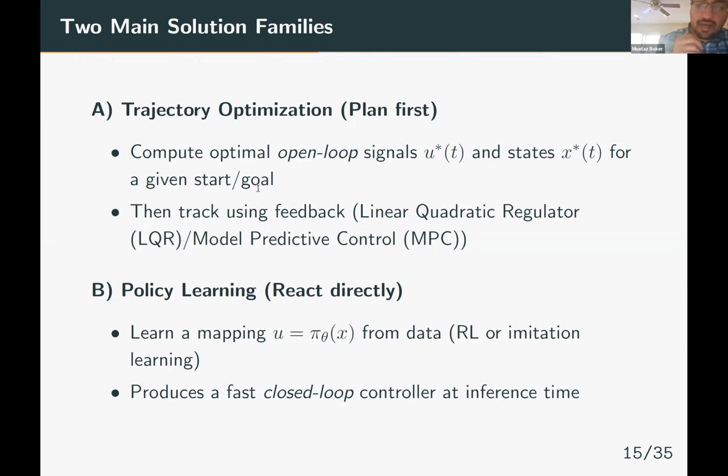So basically, we define an optimal control problem and we solve for trajectories. Here is the trajectory for the optimal controller that, if you would apply it to the system, will give you this optimal state, right? This is done offline, and then you take that and you solve another tracking control problem, where you want to drive the error between U and U star to zero, right?